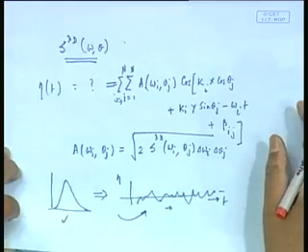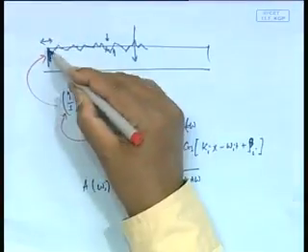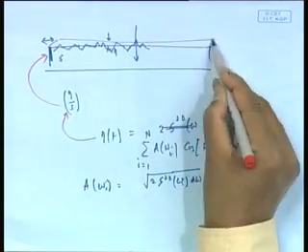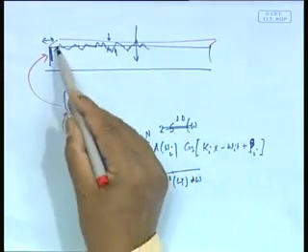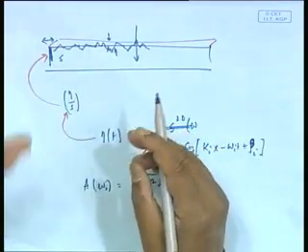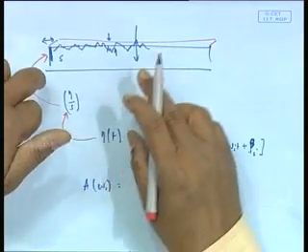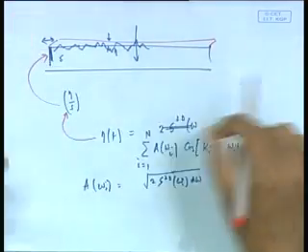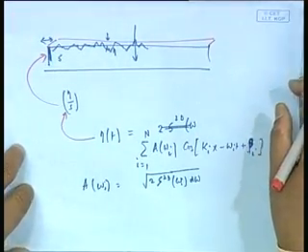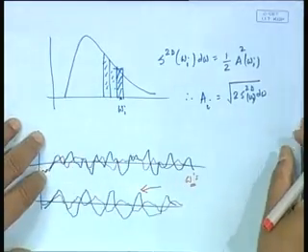In fact, I have to correct that. We can create the spectrum time signal this way, but I really cannot create waves in a long tank using a 3D spectrum, because in that case I am sending waves in only one direction. For this purpose I need a so-called wave basin, which looks like this.